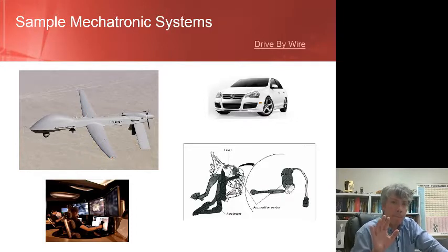Anyway, the gas or the diesel pedal, the throttle, like I said, goes to the computer as a requested signal. See, here's the thing. If it didn't work that way, I would be able to mash the pedal and generate plenty of black smoke out the tailpipe, just like the big four-wheeler trucks that are diesel can do. Now, if you think about what that means, that cloud of black coming out of the engine is actually unburnt fuel, so it's inefficiency. It's fuel that went through the engine but didn't help push the car forward.